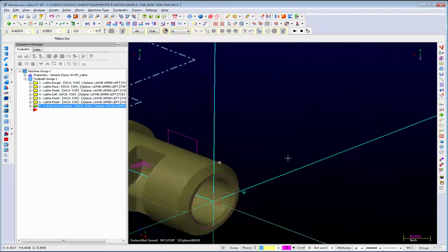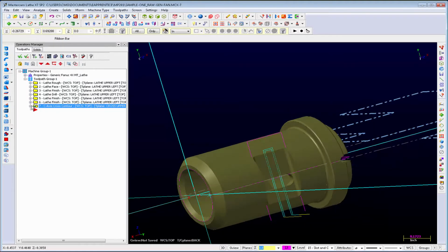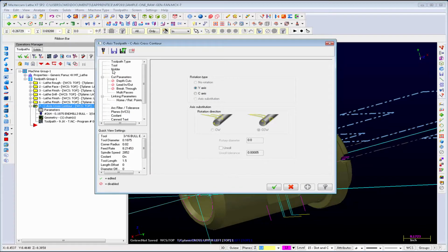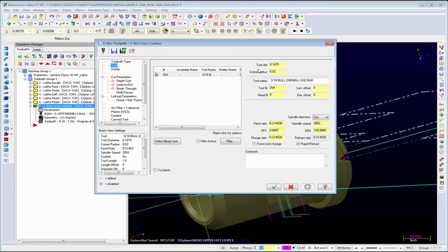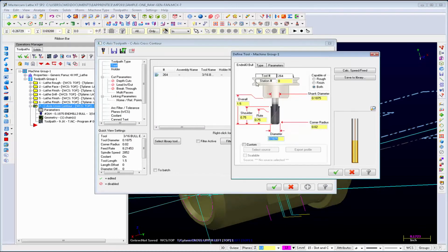That was our big dilemma. Oh, my tool has H0D0. And it's also tool 64, which isn't going to work at all, right? Because this machine might only have like 12 or, I don't know, 16 tool stations or something like that. So depending on how you have your posts set up, you might have this as tool number even 264.